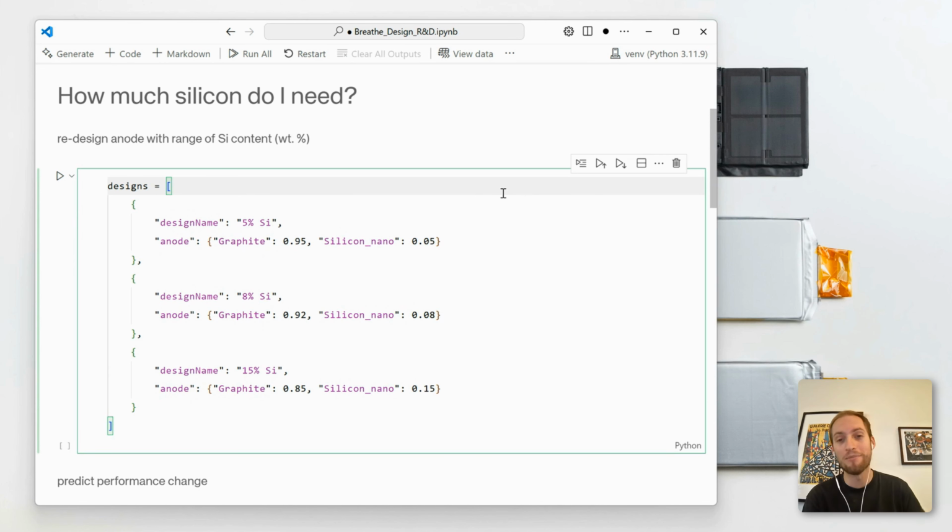It's also great at adding more problems to development and more risk. We all know it swells a lot. We know that the rate of graphite loss and silicon loss is not equal, so that might have challenges for control and estimators. And it'll be costly too. It's a more novel technology, less established than graphite, so the cost of higher silicon needs to be worth it. So there's a balance here of what's really needed for this next product.